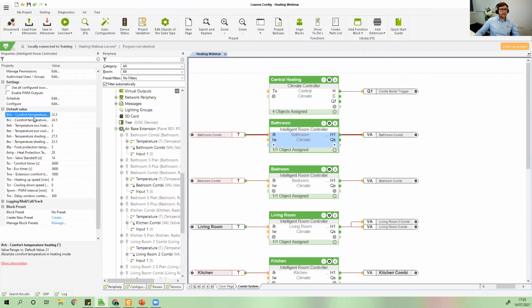So you can see we have a heating comfort temperature and a cooling comfort temperature. This is new. Previously, there was only a single comfort temperature, and then you set a tolerance each side. And you had to hit that tolerance above or below before it switched from heating into cooling mode. This is no longer the case. You now have two comforts, one for heating, one for cooling. As soon as you exceed either one, the mode switches.